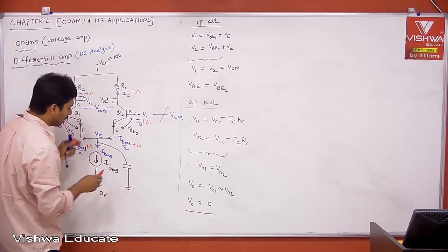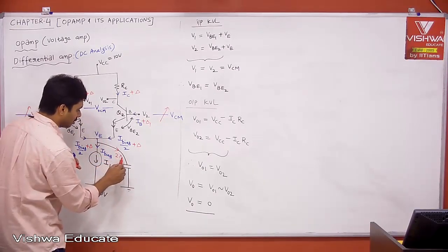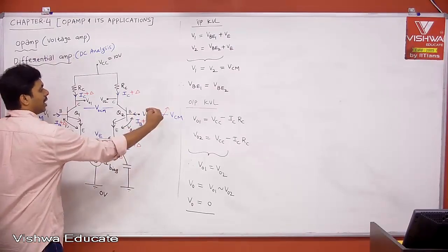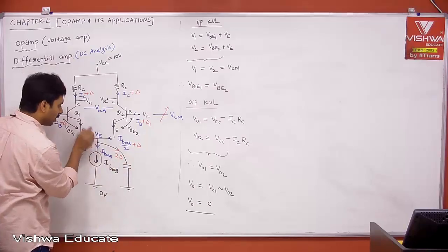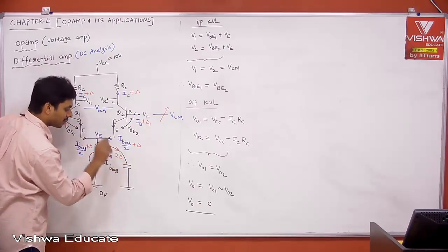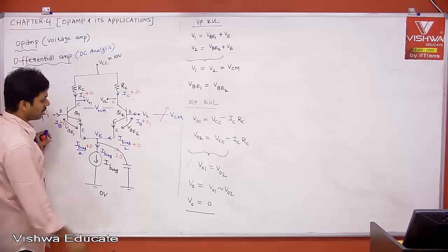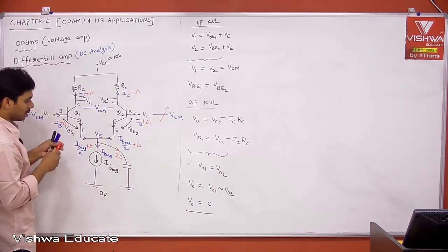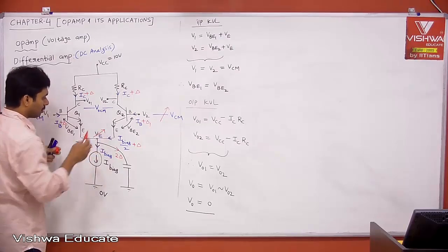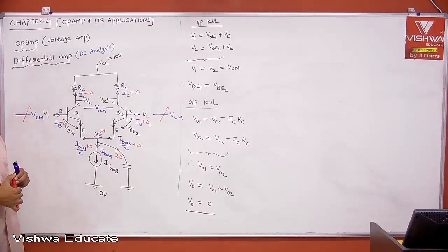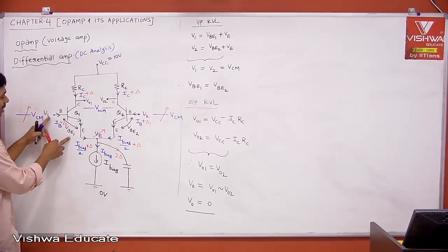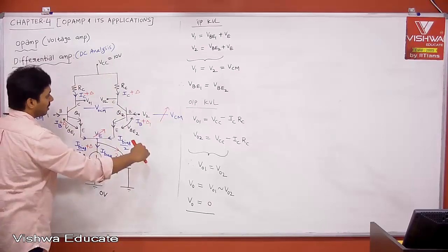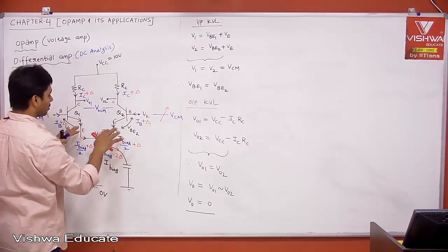Then the 2 delta is entering into what? The 2 delta is entering into the capacitor. Before, if you don't vary your common mode, then your capacitor is charged to VE. But now, because extra current is flowing through the capacitor, the voltage across the capacitor is increasing. Then your VE will increase. When VE is increasing, then what will happen? Your VBE will decrease. IB will decrease. IC will decrease. Then IC will come back to I bias by 2, I bias by 2. Done.